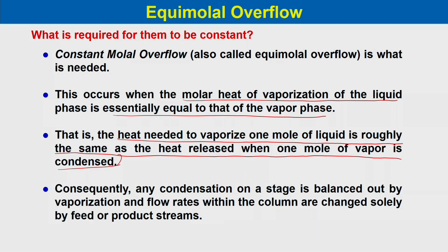Consequently, any condensation on a stage is balanced out by vaporization, and flow rates within the column are changed solely due to the feed and product streams.